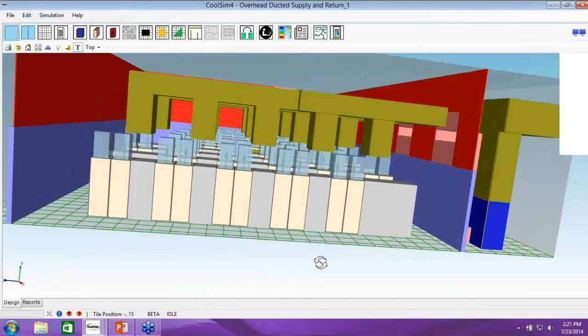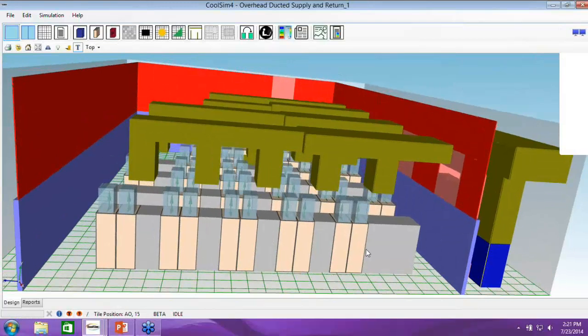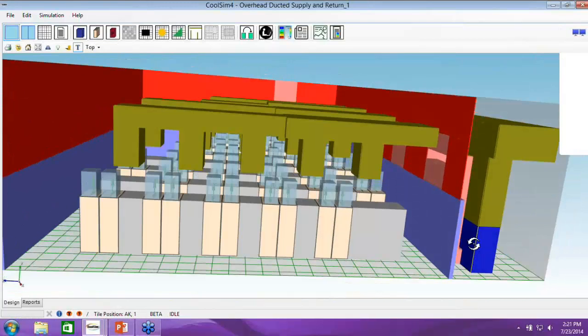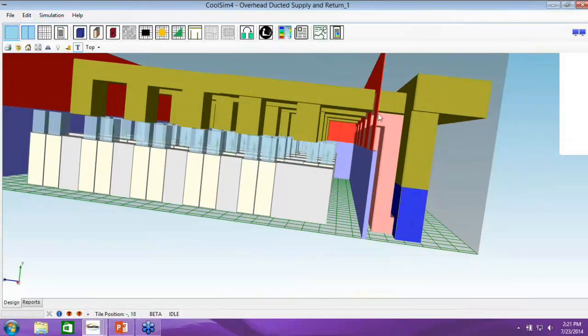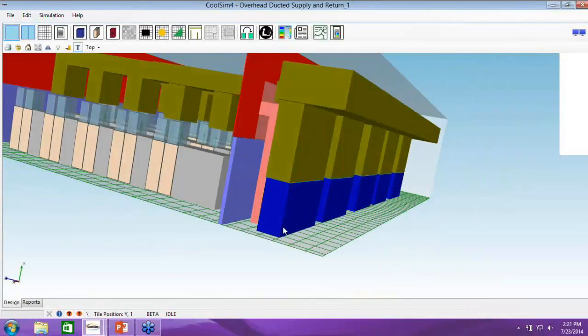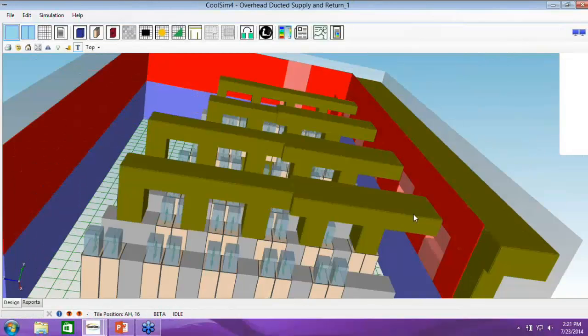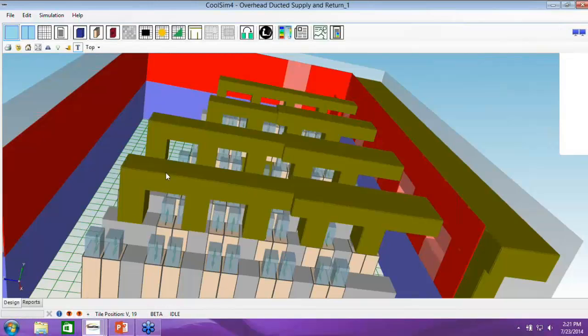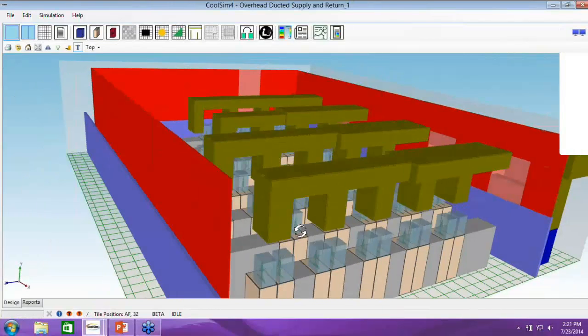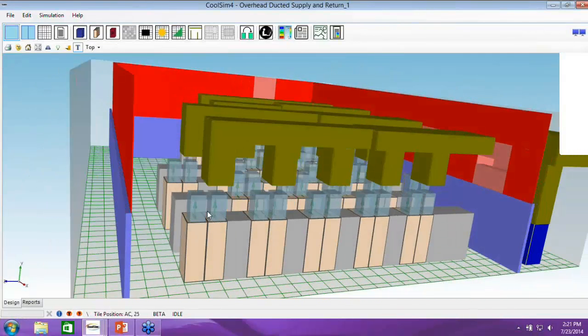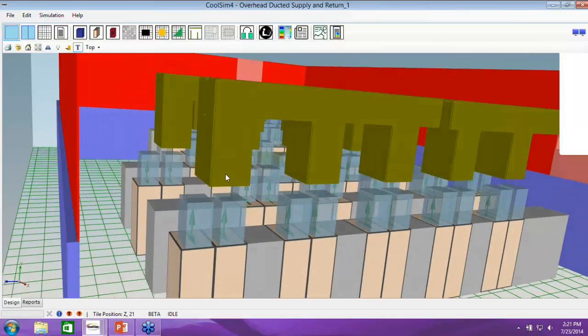You see here, this one, Magnus, is ducted supply. These are upflows. So the hot air is coming back, being pulled through these ducts into a classical upflow cooling unit, and they're being piped up into a big header and then being supplied to these series of subducts and then down into the cold aisle. Sometimes they call these designs a bathtub design. It's because you're pouring into a bathtub, or the cold aisle.